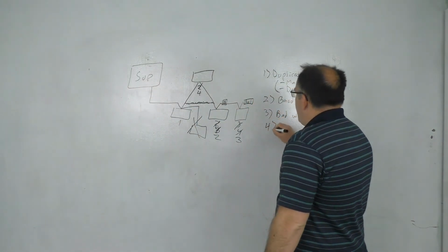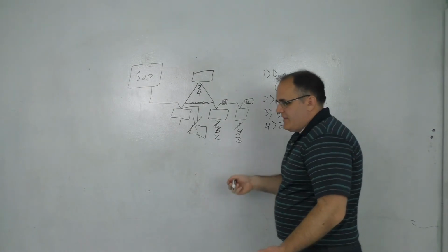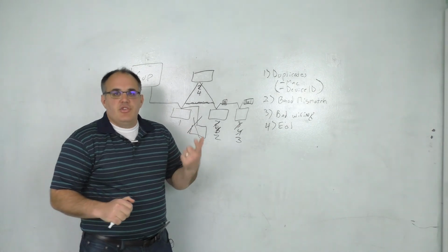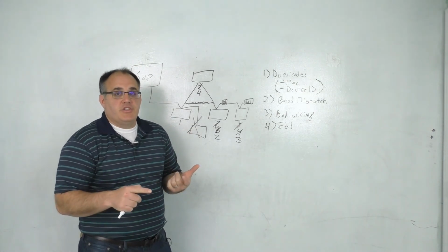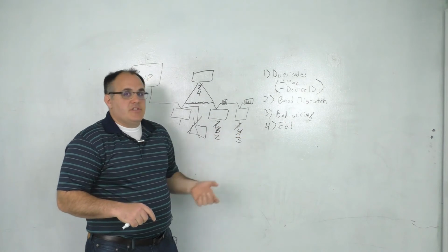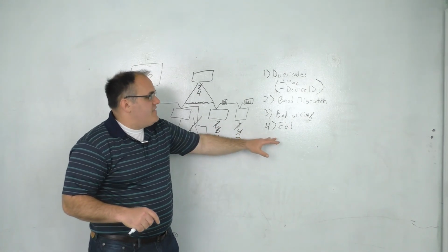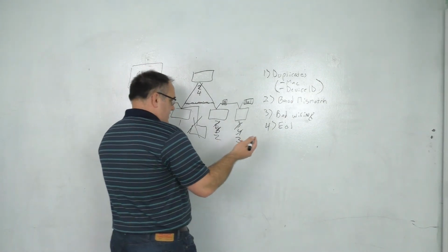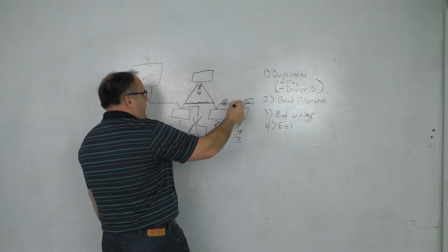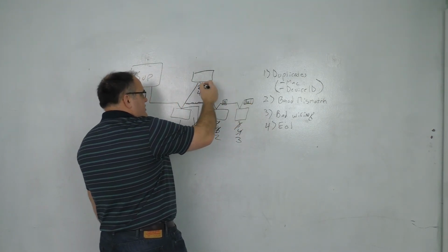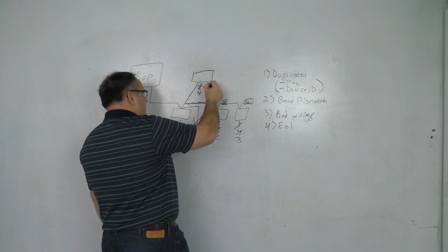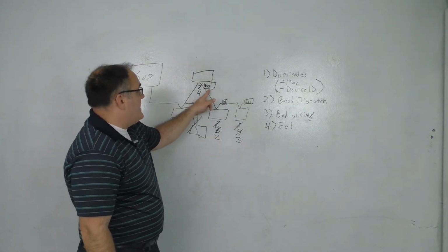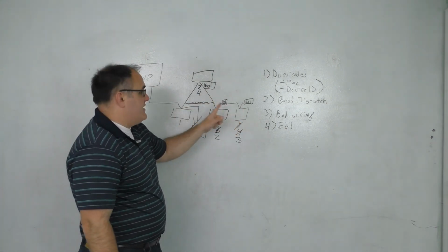From here, we move to end of lines. Now, some manufacturers have the capability to put the end of line switch on their controller, and you don't have to use a 120 ohm resistor, you just flip a switch on the controller. Well, sometimes those switches get flipped by accident, and that causes us to have extra end of lines, which makes the trunk think. So for example, we've got an end of line here, but what if on this new controller, by accident, we put an end of line here? Well, this may make the controller think that the trunk ends right here, and you all of a sudden don't see the rest of the controllers.